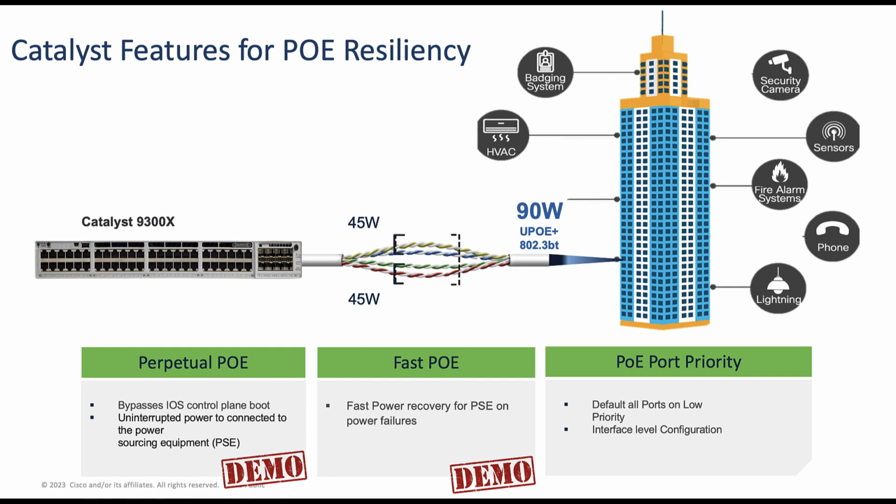Ever since 90 watts of PoE power was made available and ratified in the PoE Plus and IEEE 802.3bt standards, we have seen a rapid adoption of PoE power as a main source of power, an alternative to the traditional AC power systems. This PoE power is now powering building management systems, smart lights, point and zoom cameras, laptops, and so on. And this started enabling smart buildings overall.